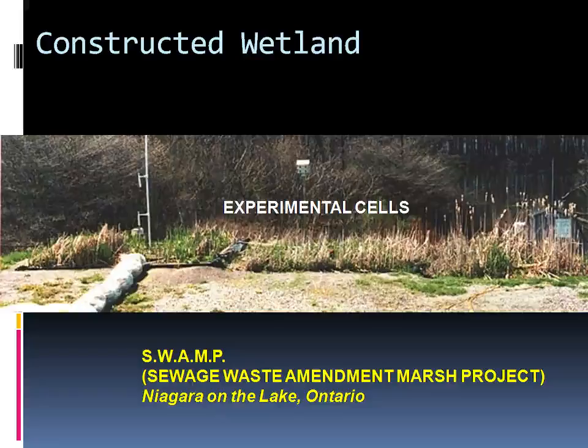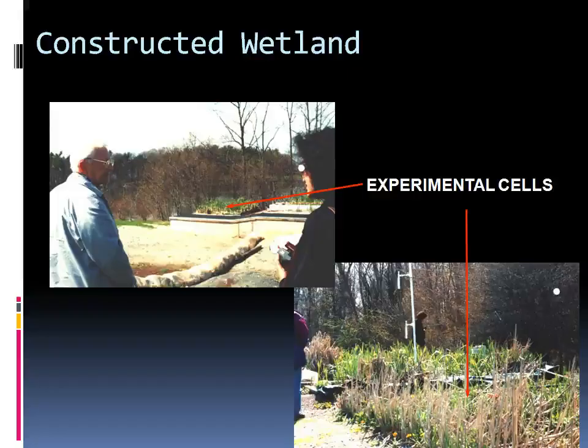The primary treatment is completed when the effluent, from which grit and sludge have been removed, is treated with chlorine gas before discharge into streams or rivers. Chlorine gas is added to destroy disease-causing bacteria. These are the different stages of the primary treatment process of a municipal sewage treatment plant. Now, secondary treatment employs biological methods to remove biodegradable organic waste, followed by disinfection